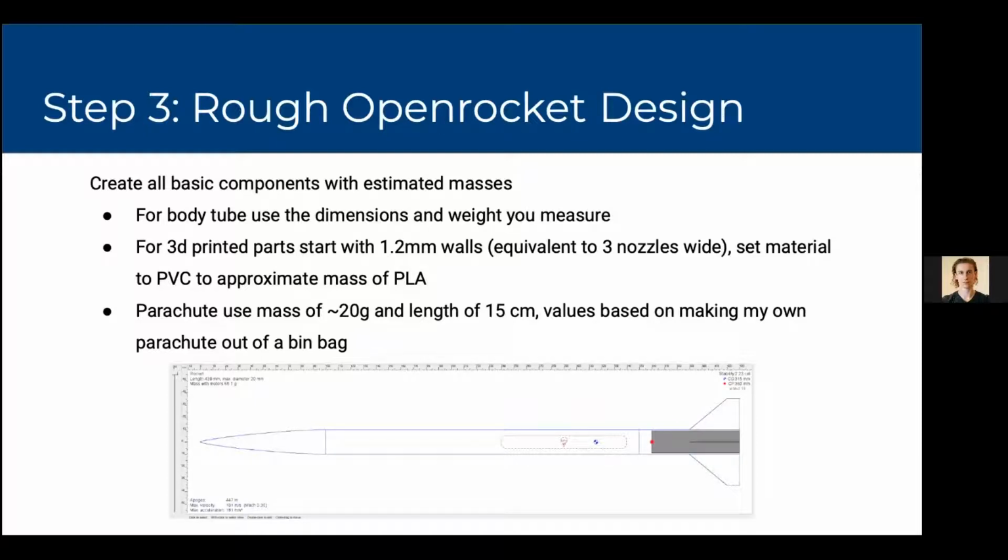It'll reach its apogee in a shorter time. And so it's suited for ejection being roughly 3 to 5 seconds after launch, depending on which motor I used. Whereas with this one, we want the rocket to be going up for 7 seconds after the motor cuts off instead of 3 seconds. So it's designed to go higher and faster.